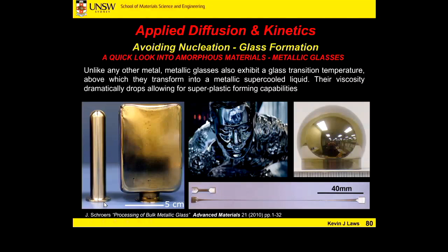This disc here is the original preform. So making a disc of material with that diameter and that thickness, we were able to blow mold this shape out of it, or this shape. So blow molding bottles out of vitreous solids. Here's another example of that blow molding. Now there's no metal, no crystalline metal on the planet that you can form to that degree. They always work harden and then they'll fracture and crack. So having this different structure is very, very advantageous.